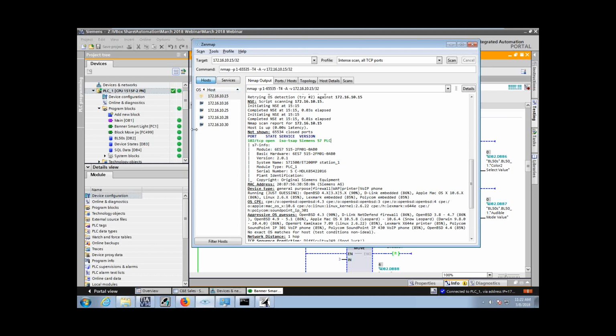The Nmap tool reported all of the NATed IP addresses here. So there's the PLC, the HMI, the Turk node, all of the things that I NATed through it could get to, and the ports that were open it discovered. So that is, again, a little startling. So what I did afterwards, after turning on the firewall, is I ran the tool again. And we'll take a look at the difference.